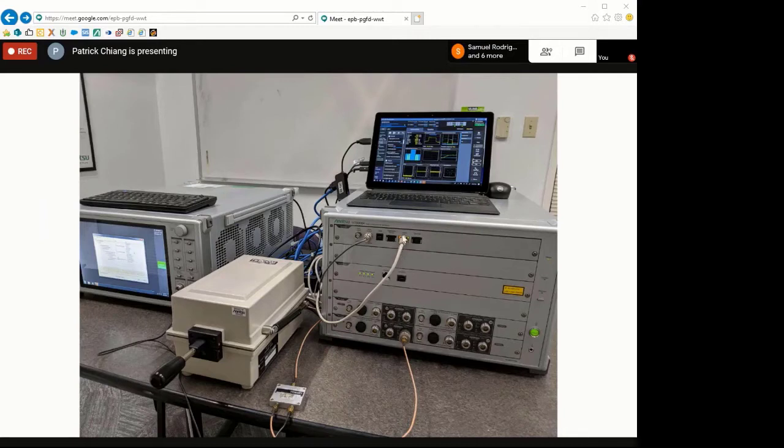Other than RF cables, there are two cables connected on the MT8000A. In the middle top, there's a white Ethernet cable. This cable runs to the control PC. And then there's also a BNC cable, the synchronization output. This will be fed to the MT8021C so that the LTE base station can be synchronized with the 5G base station.